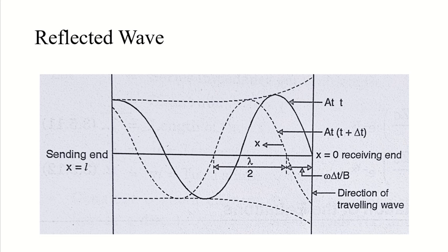With DC current, no such thing happens, because in DC the current is uniformly distributed and flows through the whole cross section of your cable, or cross section of your conductor. So there is no skin effect in DC, but there is a skin effect in AC, right? And there are different remedies to overcome this skin effect. We use a conductor called ACSR, aluminum conductor steel reinforced. So there are so many remedies.